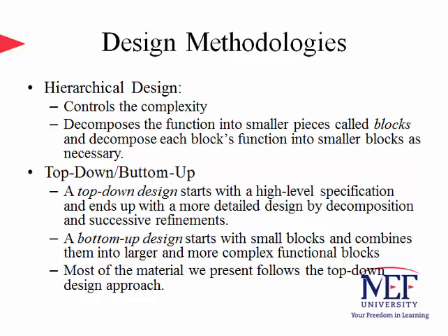So there are a few important design approaches when we design combinational circuits. In fact, those approaches are applicable to all types of designs, but here we will be given examples in terms of combinational circuits. A hierarchical design is to keep the complexity under control. This design approach divides the problem into smaller pieces called blocks to reduce the complexity of an implementation. Such an approach has the additional advantage that small blocks, also named primitive blocks, can be used over and over again by different modules later in the design.